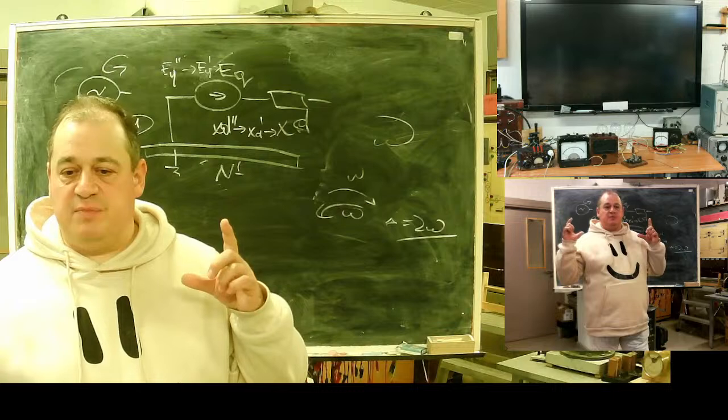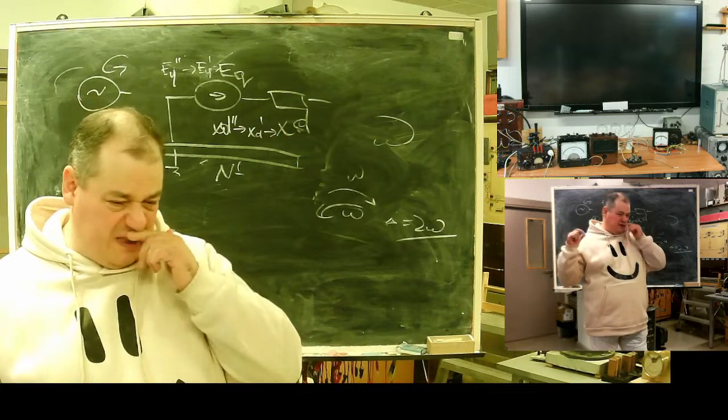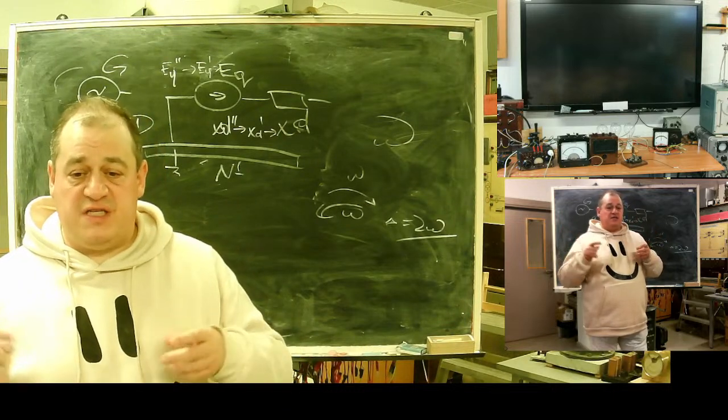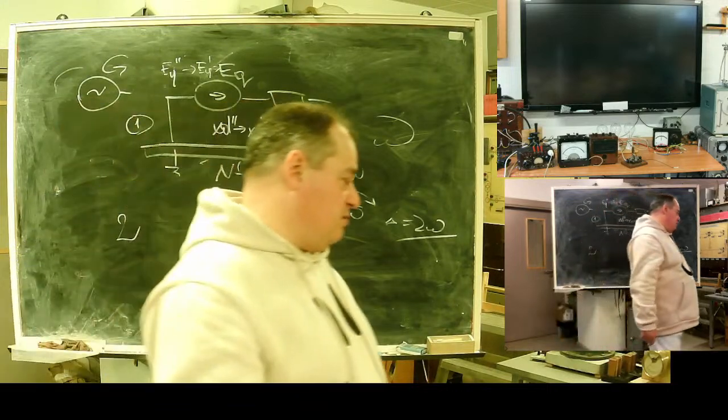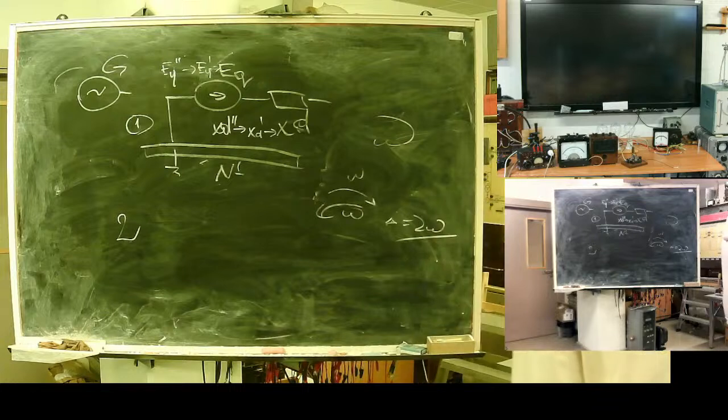Some machines had metal wound bandage holding the excitation winding. It will cause overheating of the power fixtures. It's dangerous. It causes rotor overheat.